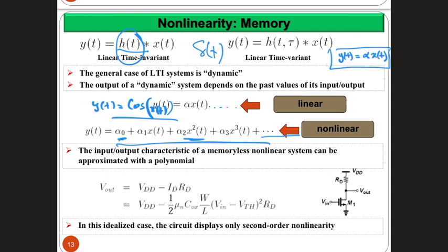All of this is just to show you that in this simple building block that we will use a lot in this course, the input-output relation is non-linear, whether I like it or not, right? The relation between the output voltage and the input voltage is a non-linear relation in general, right? I can consider certain cases with very small value of input voltage where I can approximate this to a linear relation, which is the small signal analysis.